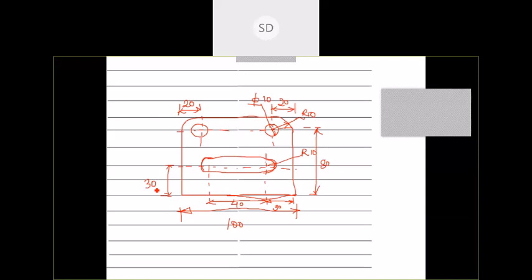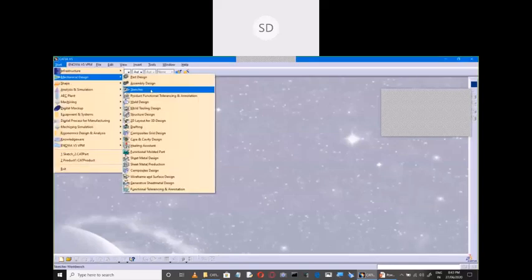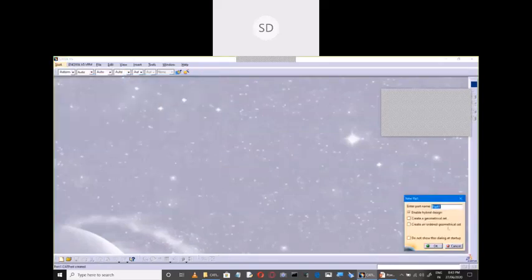So now let us go for use of other commands here. We'll go for using the command fillet, as well as trim. File, okay, I'll go for new. I'll select start, mechanical design, part.